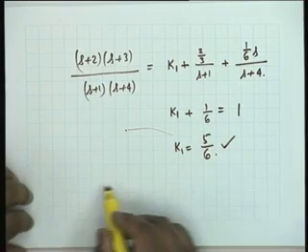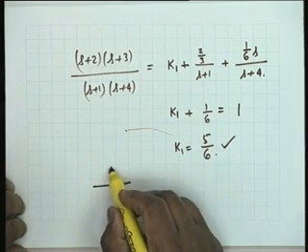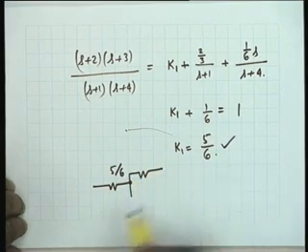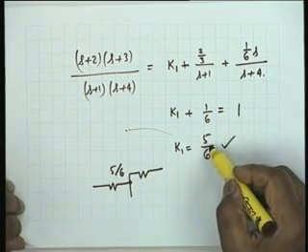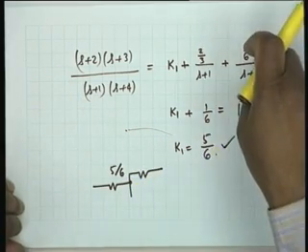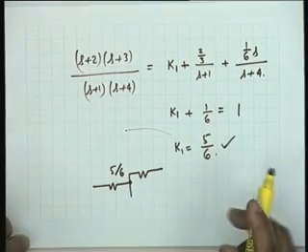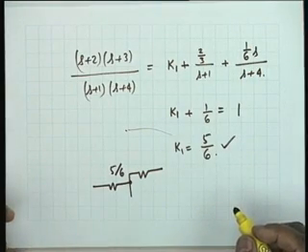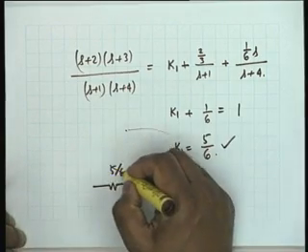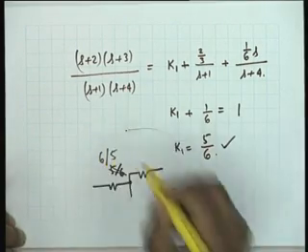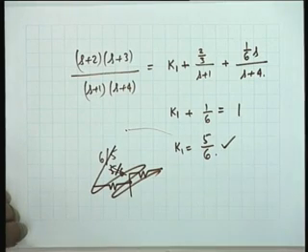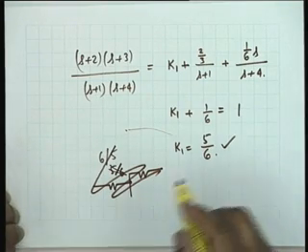So my final network is 5/6 resistance, then an RC. Don't you see the 5/6, that 1/6 is now added to that negative residue term. 6/5 resistance, because it's admittance. Oh, this is admittance, yes. 6/5. So it is not this structure at all. It is a Foster 2 type structure.